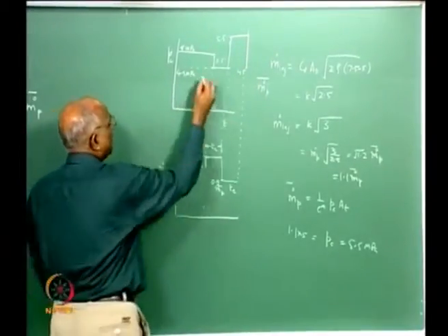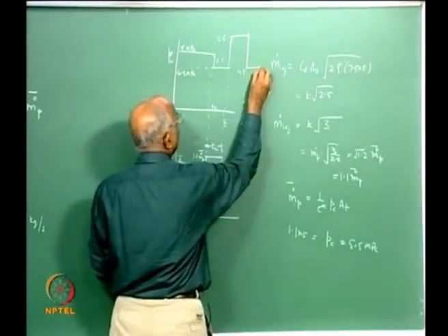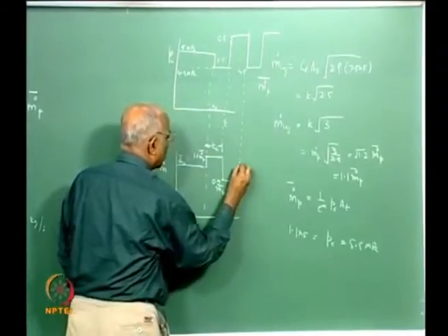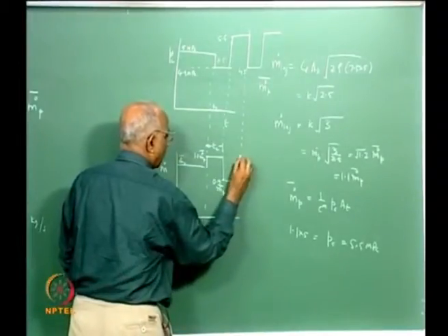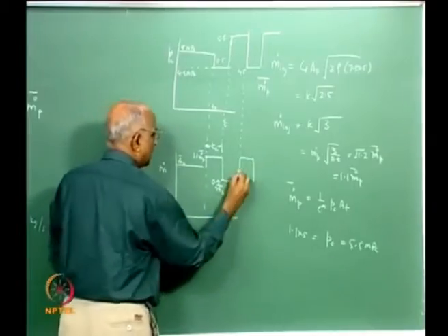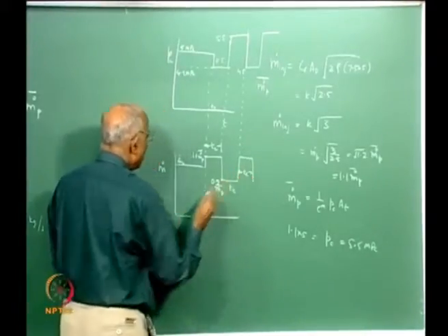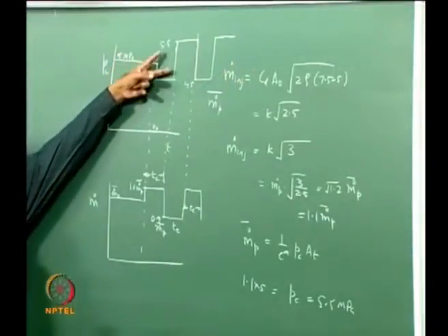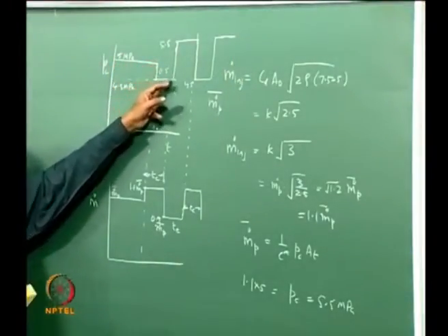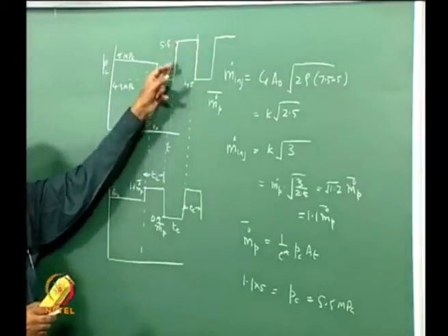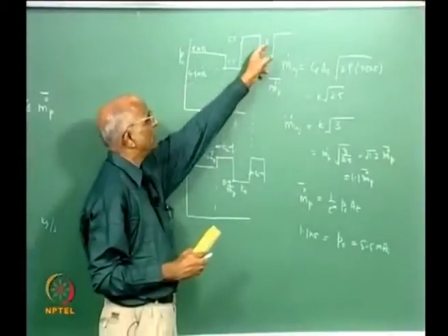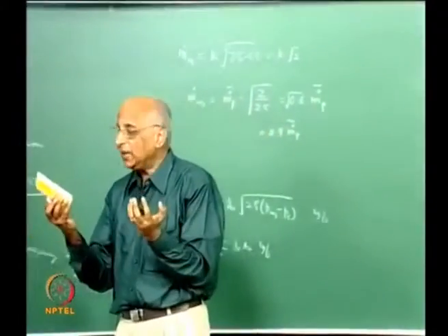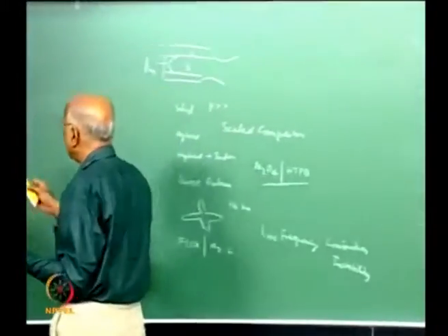And this sequence, now again it is 4.5, again after a delay time it increases, goes over here, and so on. This fellow also goes to 1.1 again, from 1.1 it falls to 1, and this delay is Tc, and therefore you find that a momentary drop of 0.5 makes the chamber pressure oscillate from 4.5 to 5.5 to 4.5 to 5.5, and out of a steady situation, when you have this delay term, you started getting oscillations.